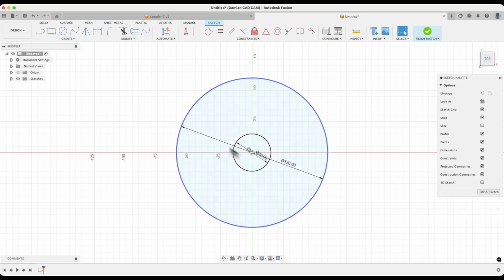Next, select Line Drawing and draw a line that starts on the circle, and the other endpoint should also be on the circle on the other side of the x-axis. Try to create this line in such a way that it is a vertical line. If it doesn't turn out that way and you create the line differently, we will simply apply the appropriate constraint here. Okay, we have two such lines, and I will draw a third line that will pass through the center